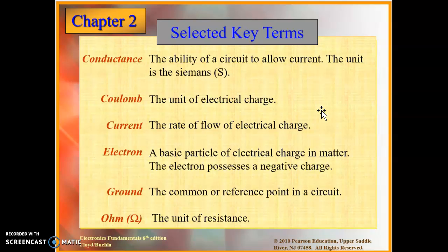Later, when we start doing nodal analysis toward the end of this class, we will see that our ground is not always going to be our point of reference. So it's important to always understand that the voltage we are dealing with is a differential voltage, a difference between 2 points. So the value we have has a reference point. We know ohms are the units of resistance, represented by the uppercase omega.